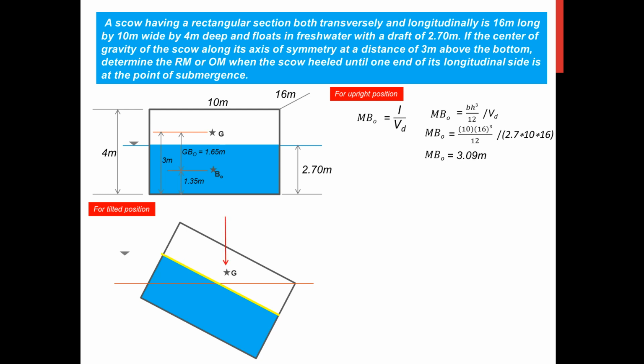We locate here the center of gravity with the weight. Now take note that this is 5 meters because we have an axis of symmetry intersecting the liquid surface. So there will be a corresponding angle here out of the triangle formed. This is actually the angle of tilt as mentioned earlier.